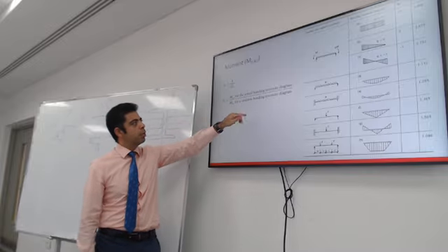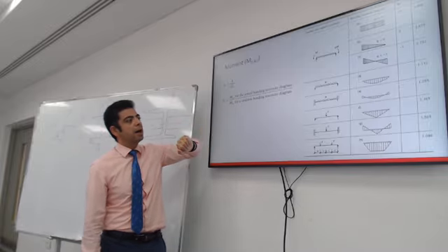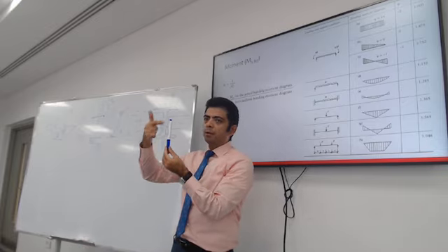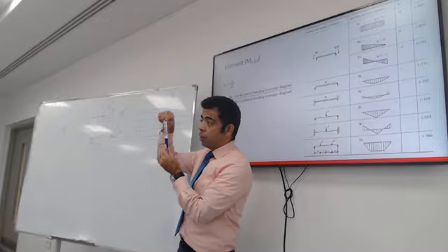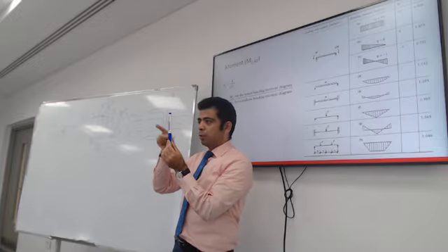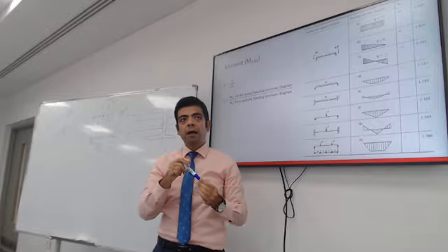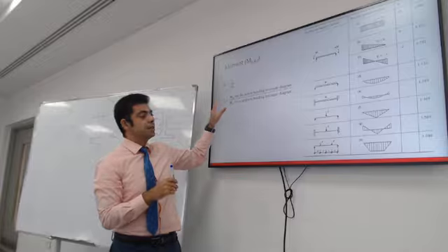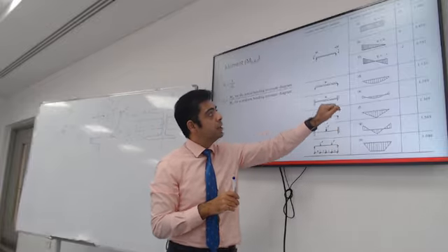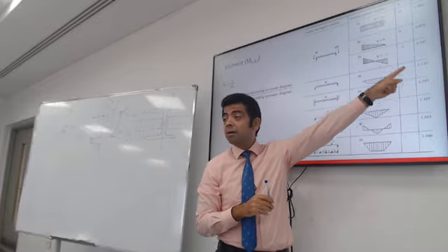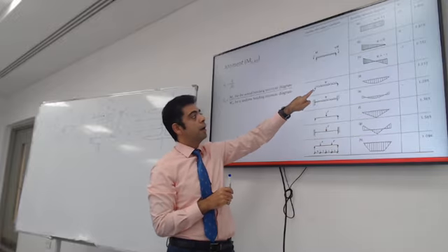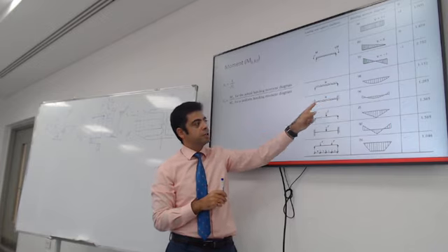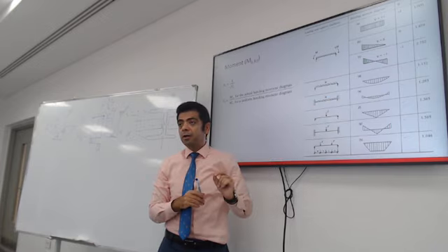There is a factor in the equations in the previous slide that depends on the ratio between the actual bending moment and the uniform bending moment. This is to account for a column that has load in between both ends. If there is only moment from the eccentricity, the moment diagram will be linear. So if you have anything other than a linear bending moment, you will probably need the C1 factor, and the code equation tells us how much C1 you use relative to the end conditions and the load pattern.